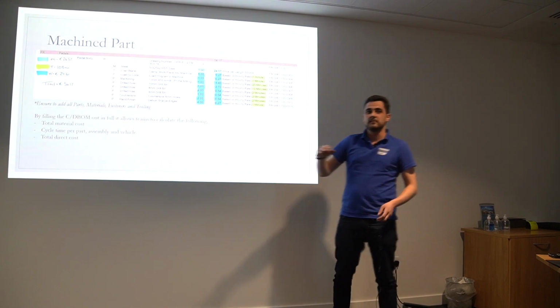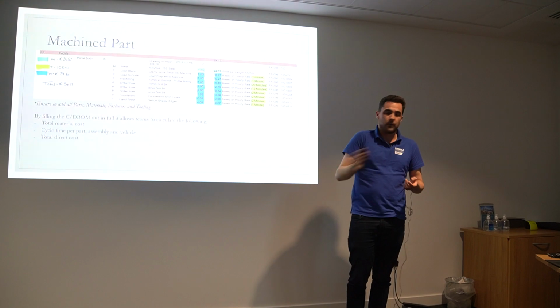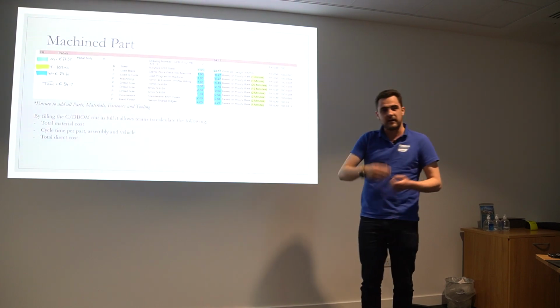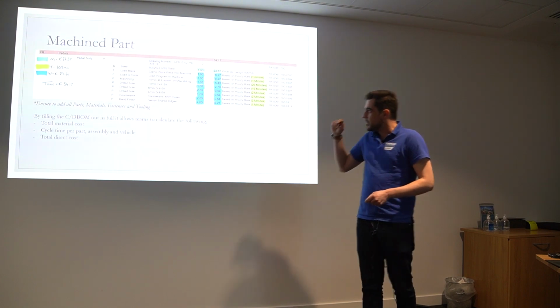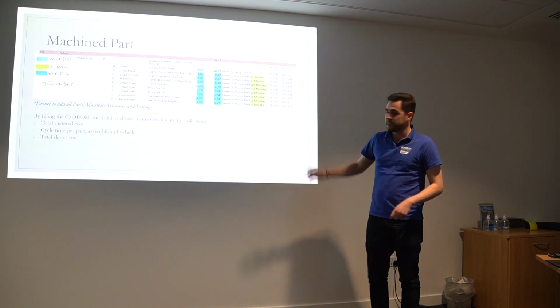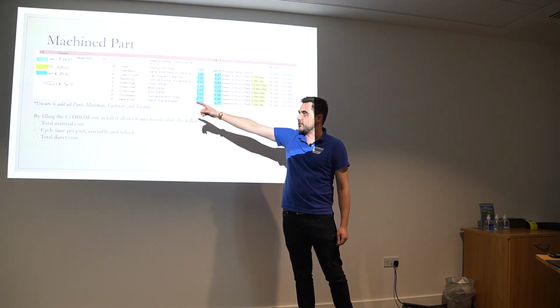Last bit, and I say for all of them, you need to actually finish the part, deburr it, make sure it's done. You might put oil over the top of it, or you might package it a certain way if it's a fragile part. Make sure that's included. The benefit of writing everything down, the amount of time taken for each, the cost, the quantity, is you get those figures at the end.